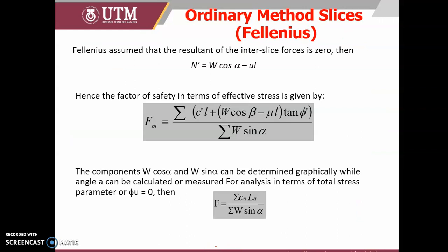So for the parallel slices method, we can use another derivation. In the parallel method, they assume the resultant of the interslice forces is 0. It means that if you have slices analyzed side by side, the first slice and the second slice don't have any E. So the resultant of the interslice forces is 0.